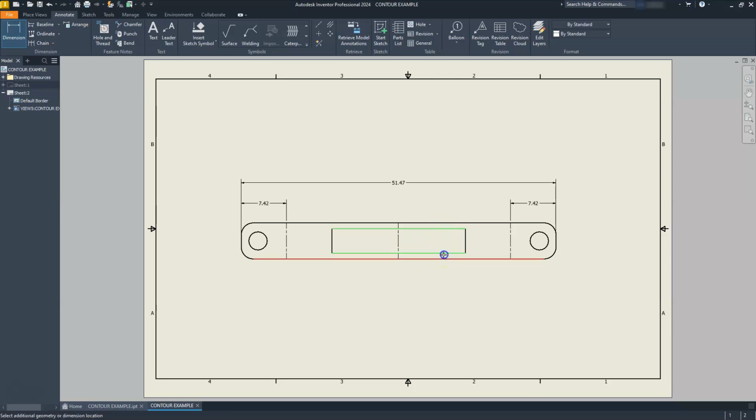And you remember that this from the front should still be sitting at 4. The location from here to here gives me that distance. And you can see that I can do a lot of things here on my flat pattern. That'll give me the overall shape of this, right? If I wanted to, I can also go ahead and put my center marks that are located on here.